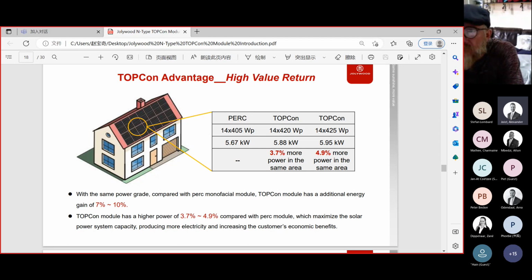And in my opinion, one of the greatest things is actually the warranties and the durability, especially having a glass module. If something breaks, normally where we see issues in solar modules is with the back sheet. If something happens, it gets pierced through the back or scratched on the back sheet. With the glass module, the durability is much higher.